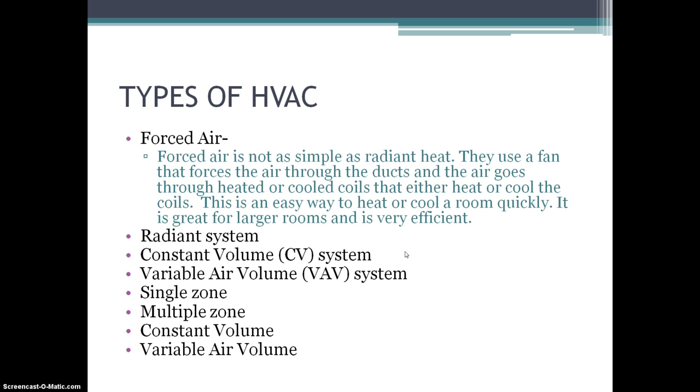So how it works is the thermostat will tell if the room is too cold or too hot, and the air handler will kick on, drawing room air from a cold air return through the ductwork into the furnace heat exchanger, a metal chamber around which air flows. The burner or electrical heating elements turn on, or the heat pump engages to heat the air as it moves through the air handler. The blower then forces the warm air through a network of ductwork back to the room. The cycle continues until a comfortable level is reached and the thermostat turns off.